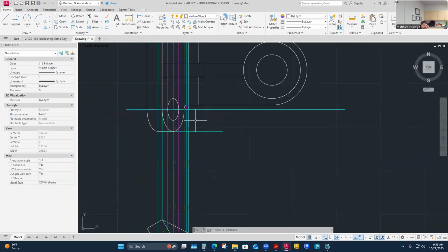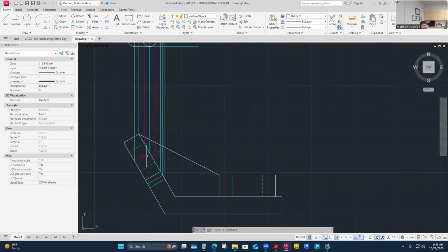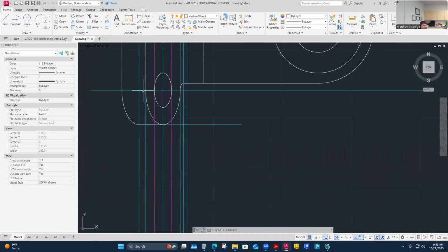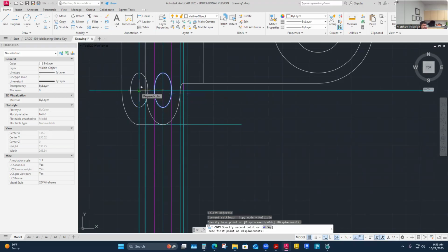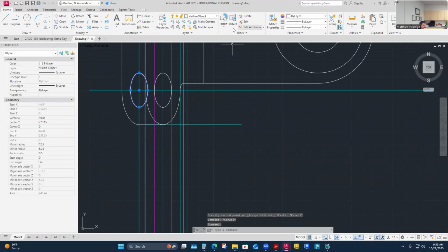And then it exits through the plate as well. So I have to consider that it will go through here and through the backside where it exits. So I'm going to make a copy of that, making sure it's on the same concentric line this way. I just need to make sure that I've projected the center line up, which I have already. So at this point right here, I need to make a copy of this thing and place it back here where it will exit, right? And eventually what I see is I'm going to have a piece that I don't see at all. That's going to be the hidden feature. It'll be buried in material. Unless I have X-ray vision, I won't see this. So I'm going to move it to a hidden layer.